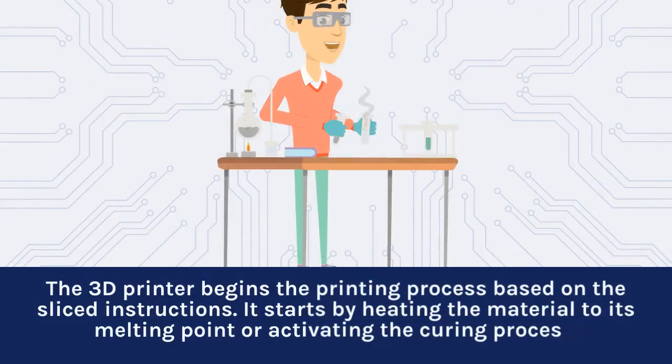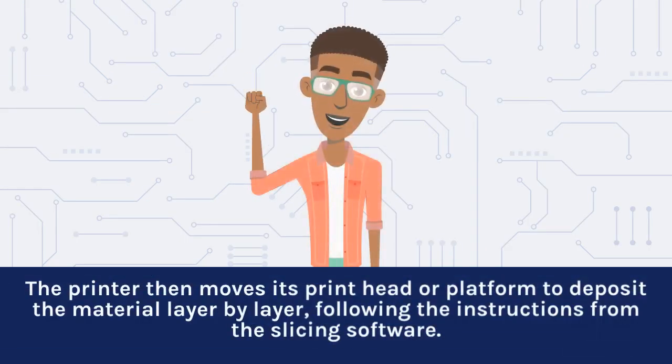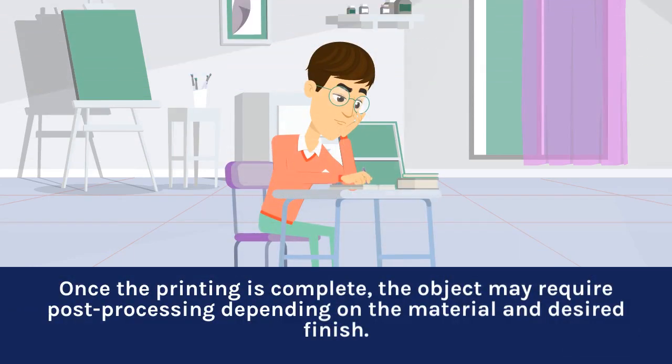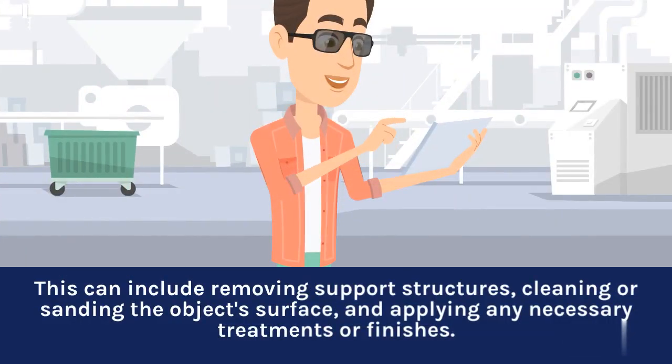The 3D printer begins the printing process based on the sliced instructions. It starts by heating the material to its melting point or activating the curing process. The printer then moves its print head or platform to deposit the material layer by layer, following the instructions from the slicing software. The layers gradually build up, adhering to each other to create the final object. Once the printing is complete, the object may require post-processing depending on the material and desired finish. This can include removing support structures, cleaning or sanding the object's surface, and applying any necessary treatments or finishes.